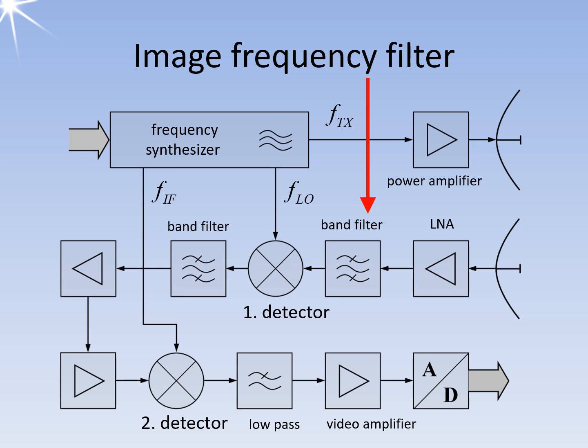The bandwidth of the image frequency filter must encompass the entire tuning range of the receiver. It's important to note that this bandwidth differs from the receiver bandwidth, which is defined by the bandpass filter for the intermediate frequency located after the first mixing stage. Consequently, there are two conflicting requirements for a receiver: the need for a larger tuning range and the desire for a low intermediate frequency, IF, that serves its purpose effectively.